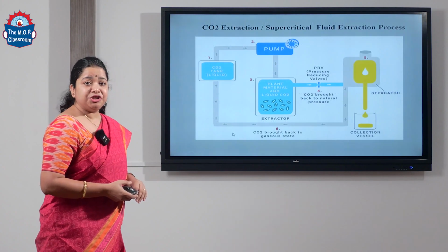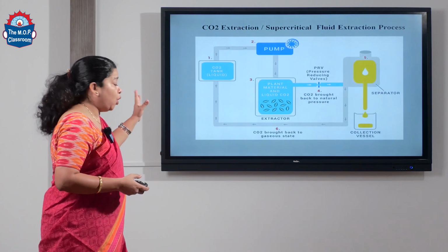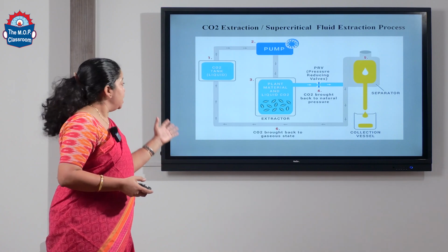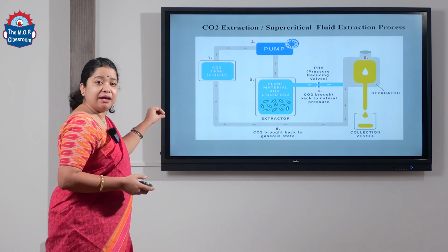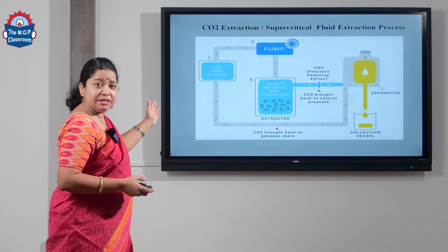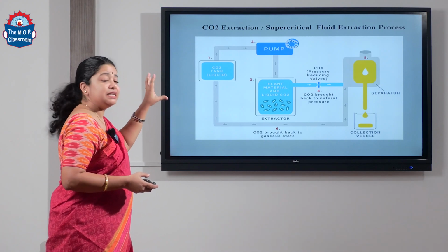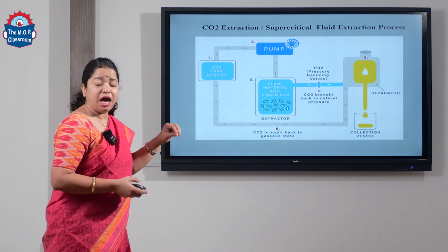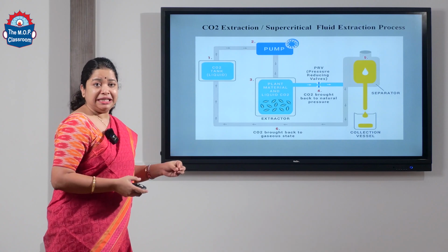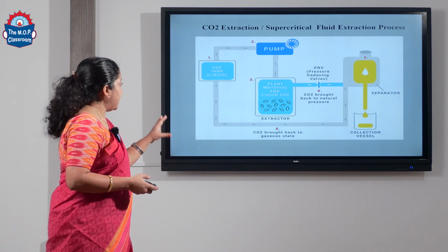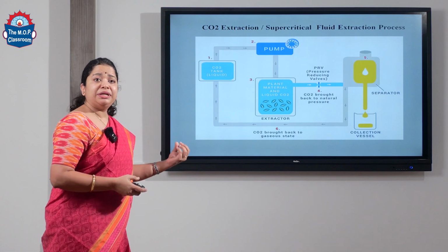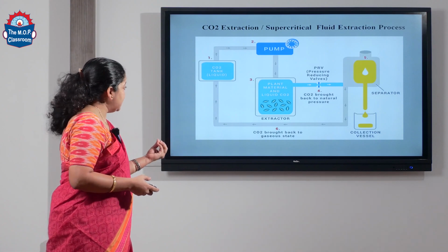In carbon dioxide extraction, as you can see, there is no water source and no solvent used, unlike the other processes. This process uses carbon dioxide in the liquid state, which is pumped at a very high pressure above its critical limits and moved on to the plant or spice material. The spice material and plant material get agitated and mixed, and the volatile compounds gradually get released.